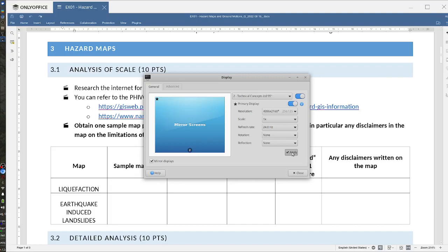What I also want to show here is the disclaimers accompanied by the maps. You have here usually an explanation here. Okay, so this is a composite map of estimates of maximum intensities that may affect the study area. So you can also see here the methods are described here. Okay. And then on the second sentence, you also have a disclaimer here that ground shaking hazard maps do not restrict construction of any structure or land development in areas, as long as it is allowed by the National Building Code or it follows the National Building Code.